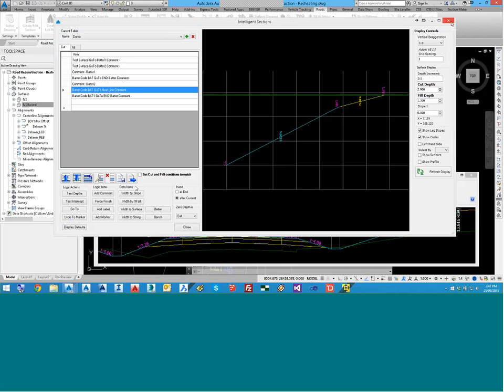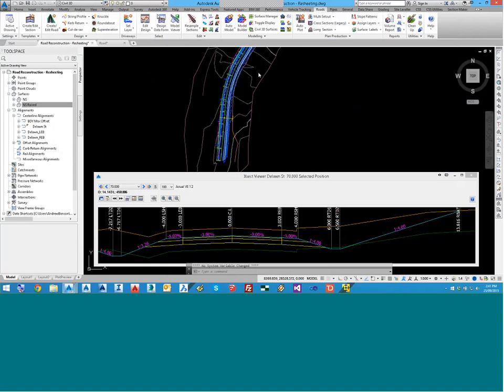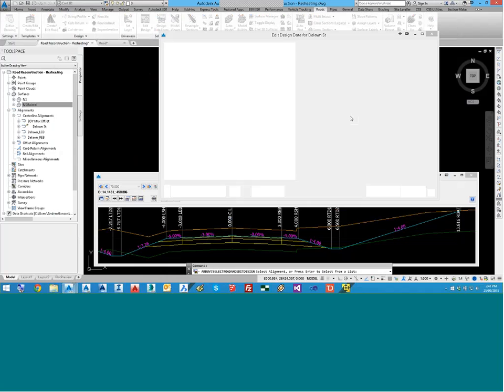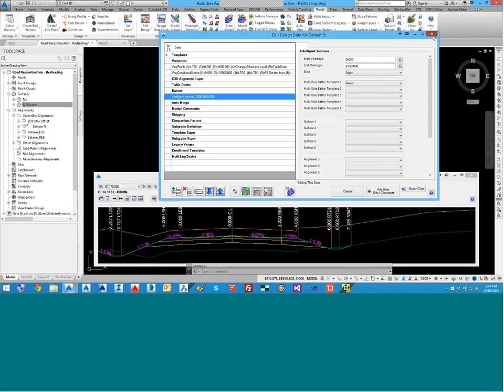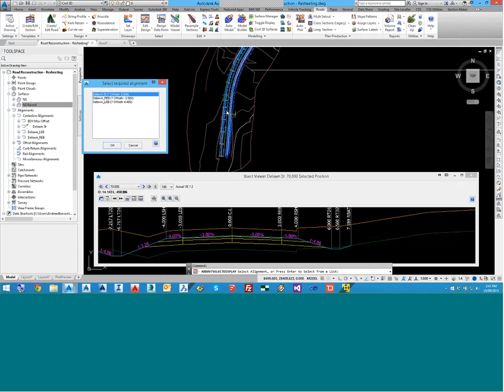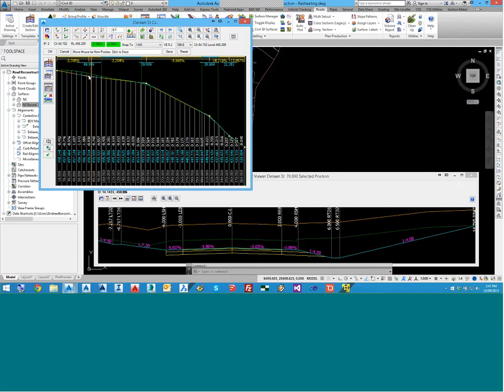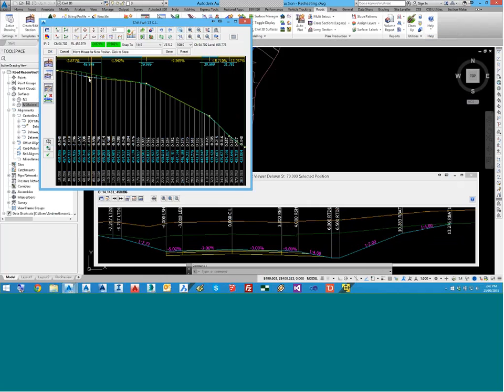So I might just finish this intelligent sections by applying it to the road. I just called it demo. I wasn't referencing any surfaces for this one, and I'll put it on both roads. Okay, so let's open up the vertical grading editor here. As I move the levels, you can see if I'm within the half a metre, it goes back to the surface at 1 in 4. But as we get deeper, it puts in those dual legs going up at 1 to 2 and then 1 to 4 to the surface, okay?